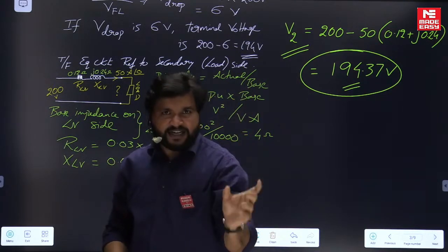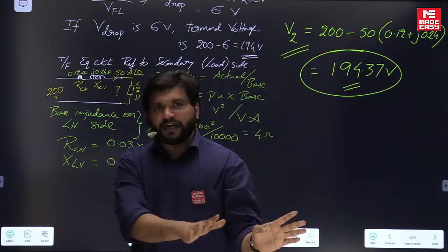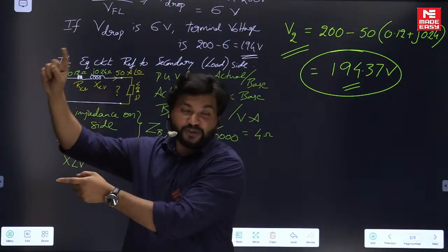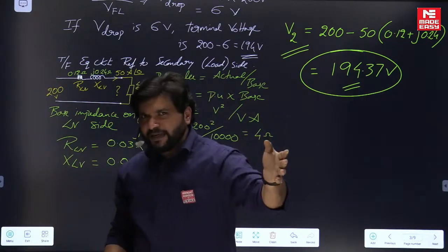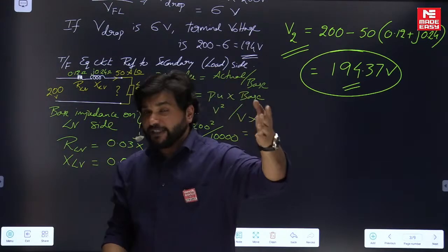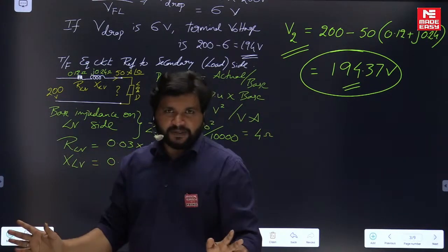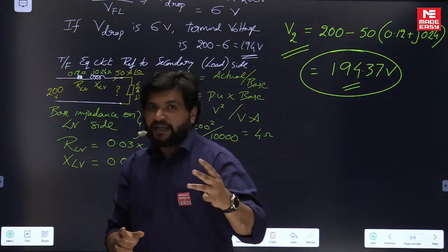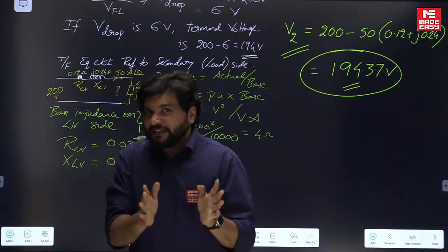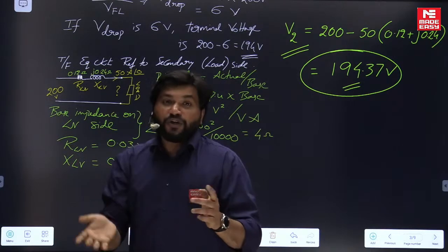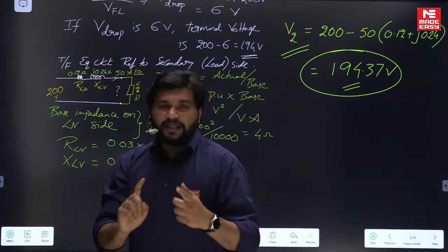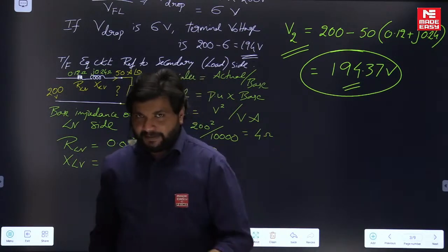Take these 3 windings, high voltage primaries, low voltage secondaries, or low voltage primaries, high voltage secondaries, anything, and connect them in star or delta. If you have 3 individual single-phase transformers connected as a 3-phase transformer, then it is called a bank.